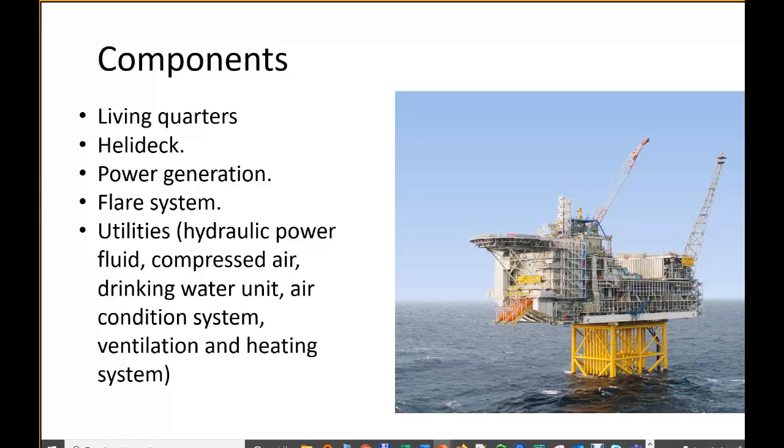So that means you have here someplace the process, the whole process that I described. And then you have the flare for emergency situations or for maintenance, or for when you have to burn some hydrocarbons just to make it safe, so that you don't have a release of hydrocarbons in your process, okay, your platform.